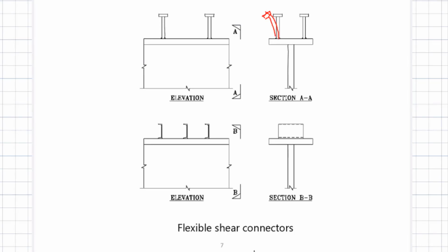That is good for me. Sometimes, after all, I want to design flexible structures that give me adequate warning. We say we have to have structures that have ductility, and then they show distress so I can correct it, and I don't want any catastrophic, boom kind of failure, right?